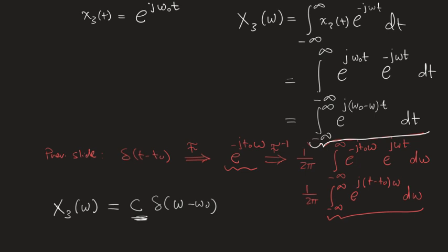But shape-wise, I had a complex exponential in the time domain. When I looked at the situation that I solved earlier, the delta in time domain produced a complex exponential in frequency, and this gives me an intuition that if I do the opposite, if I put a delta in frequency, it should produce the time domain signal, and then I solve the problem in the inverse way.